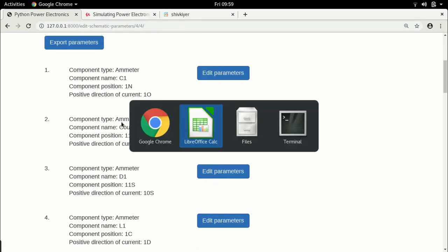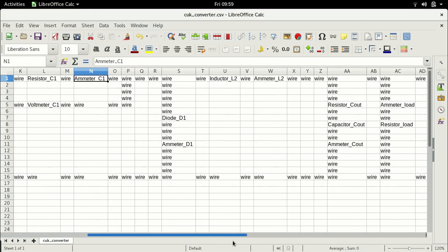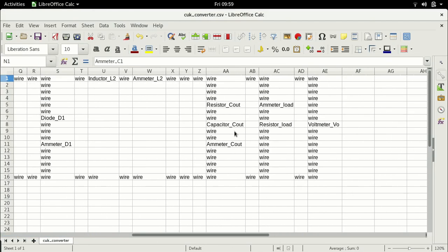The next one is C out. C out should be fairly simple because C out is here. The ammeter C out is basically, again, just like the buck boost converter, the Cuk converter has a negative polarity. So it's actually the capacitor, the positive polarity is downwards. So what that means is the current in this capacitor is entering from the bottom. So the direction of current in this branch is bottom to top.